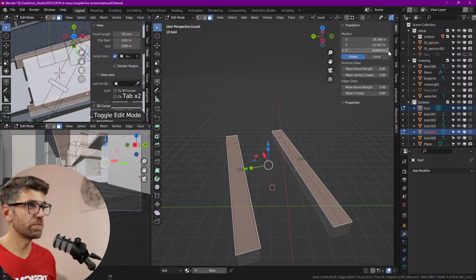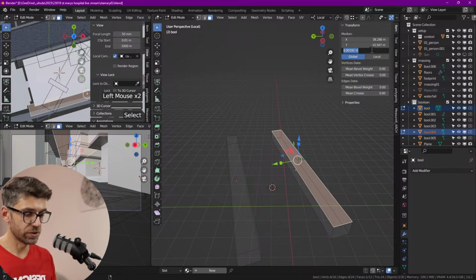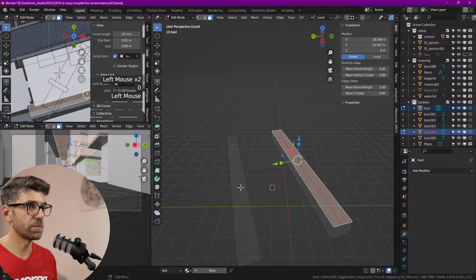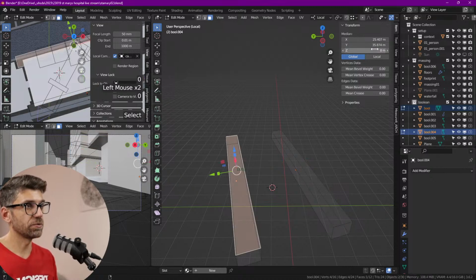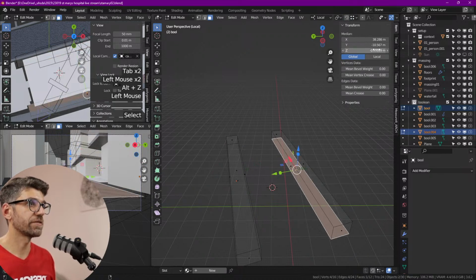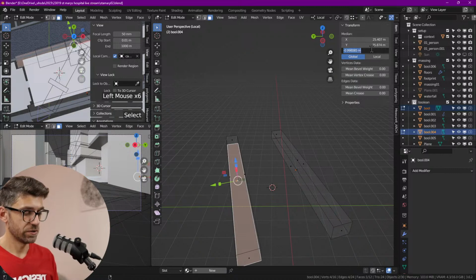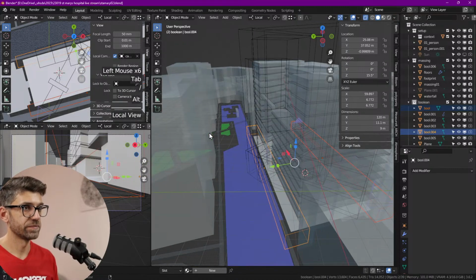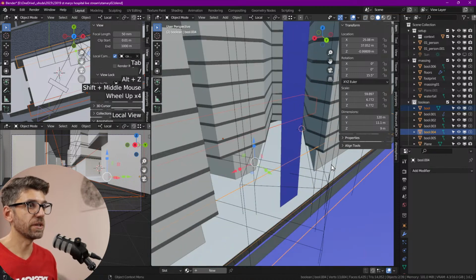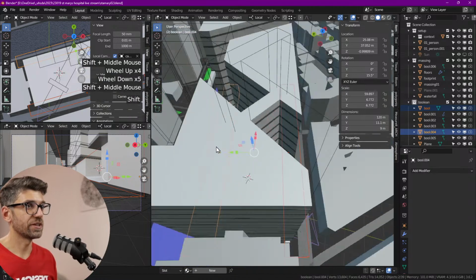Now they have some discrepancy here. That might be, it's not in calculation. Sometimes it is, but sometimes Blender makes errors as well with the numbers because it's not double float. Usually there's no problems if you work quite close to the origin. Or sometimes, you know, it does happen that I might have snapped. Yeah, it looks like I might have snapped to something that is at the wrong level. So just like to make these quite nice and even. Okay, so now we have like an 8 meter setback. That's getting really sharp, so we will need to adjust that as well.